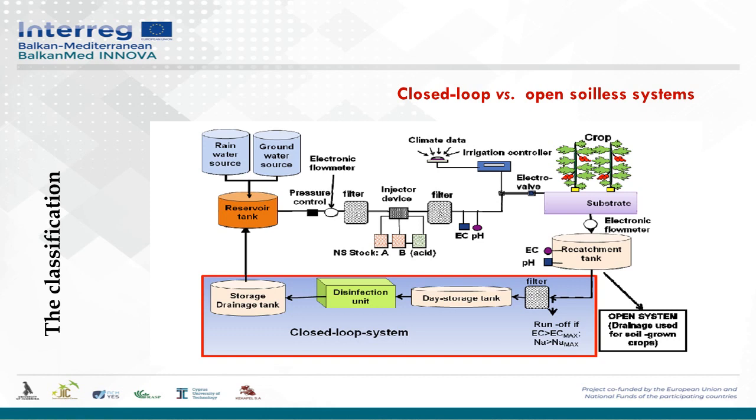It's important that you keep the calcium salts separated from the phosphate salts, otherwise we will have very intensive chemical reactions, which will end up with specific substances which are not soluble in the water.